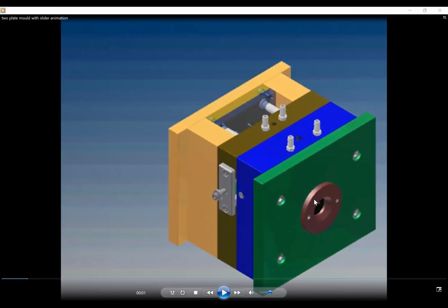So what happens is that at the beginning, the material gets into the cavity, which is located here. This is the fixed plate, and this one is the movable platen. And these are the channels through which the water is circulated to cool the material. There are some channels.